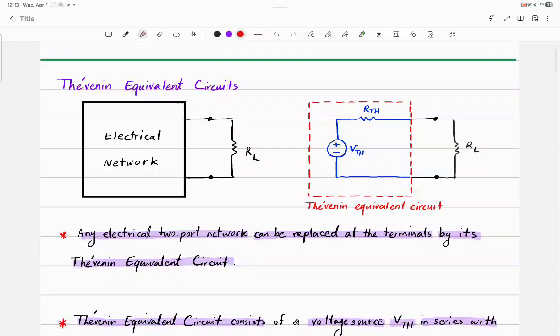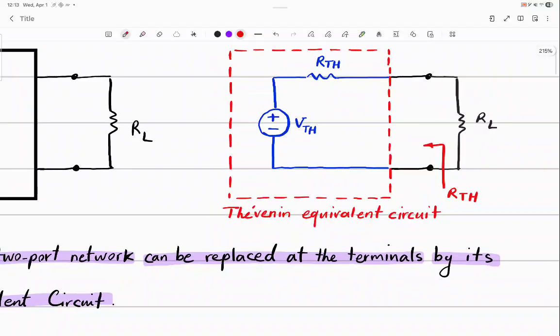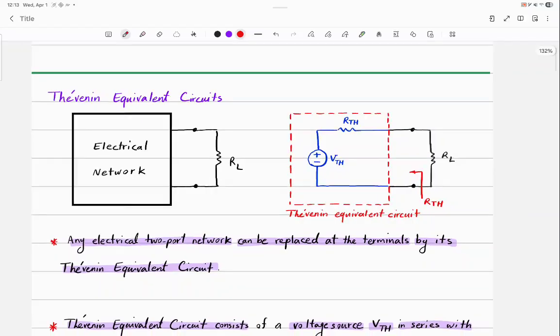I usually show it using that. This is how I show it. What does it mean? It means that if you stand at the place where your load is located and then look to the circuit, imagine that you have some superpower to sense resistance, okay? The value of the resistance that you sense or see is equal to the Thévenin equivalent resistance. Now, you don't have to have the superpower. You only have to have one multimeter to do that, okay? So that is how I usually show it. And yeah, any questions so far?